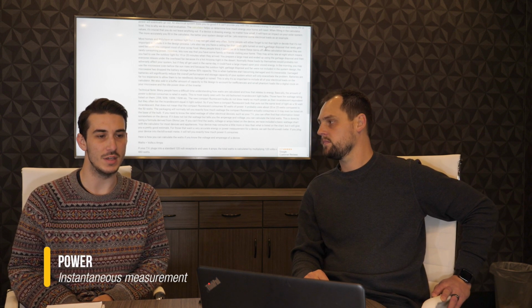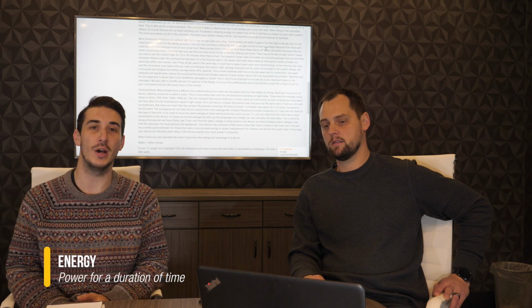Another way to think about the difference between power and energy is that power is the instantaneous amount of wattage that a device is consuming in an instant. Energy is that power over time. A kilowatt hour is a common unit used to measure energy, and that would be just like you would receive on a bill from your electric company. They would bill you for the amount of energy you're using in kilowatt hours, not in watts. A kilowatt hour is essentially 1,000 watt hours, or in the case of a 100-watt light bulb, if that was running for 10 hours, it would be essentially 1 kilowatt hour of energy consumption.